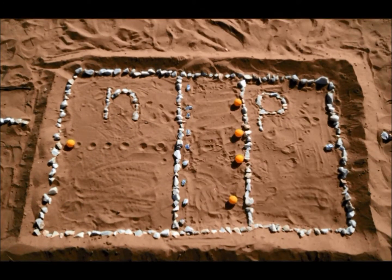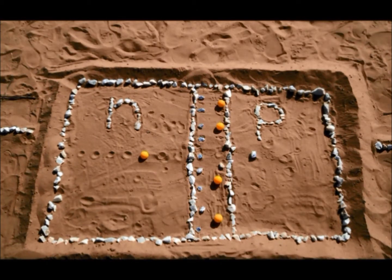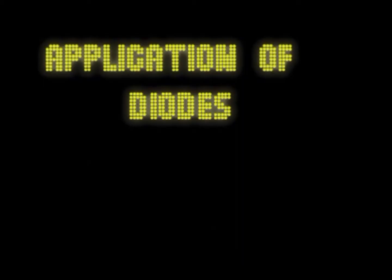In reverse bias, the negative potential at P attracts the holes and the positive potential at N attracts the electrons, preventing their combination at the junction, thus producing high resistance to current flow. This project deals with two basic applications of diodes, rectifier and LED.